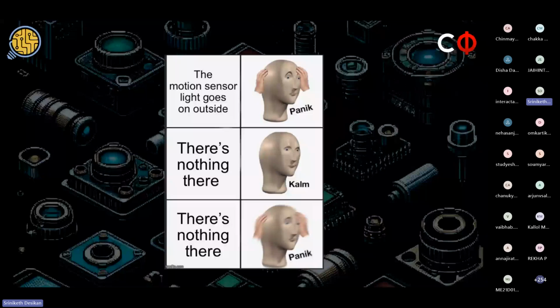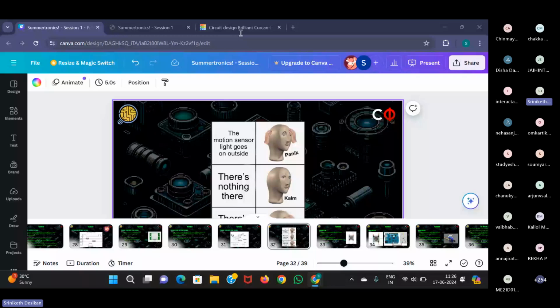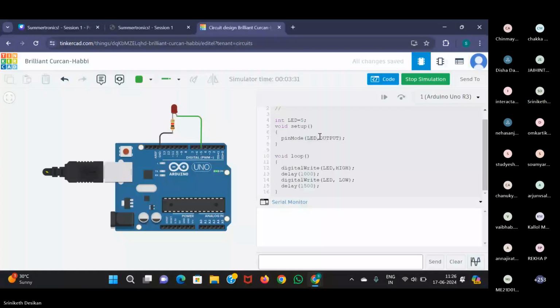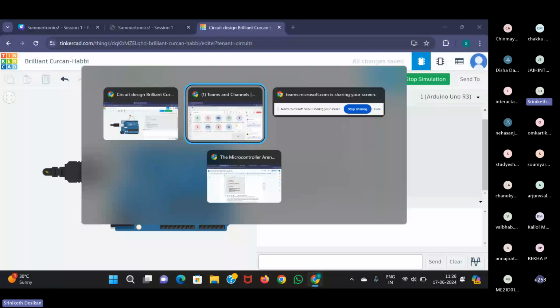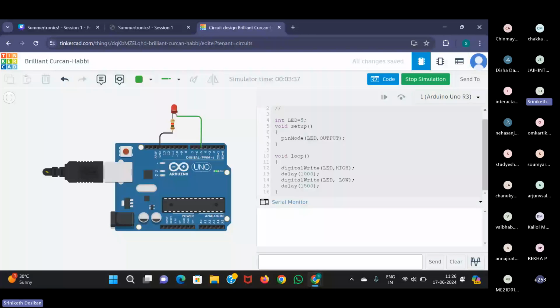Can you repeat the meaning of digital write? I'll just go ahead and do that before I hand over to Chandra for the simulations. A digital write is just to set a digital pin to high or to low, to a particular value. We are asking the microcontroller to make the pin high for some particular time and make the pin low for some time by using the delay function here. We are just asking the microcontroller to set the pin to a particular digital value. That's it.